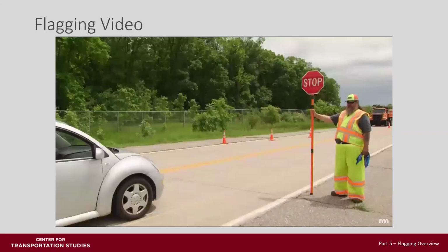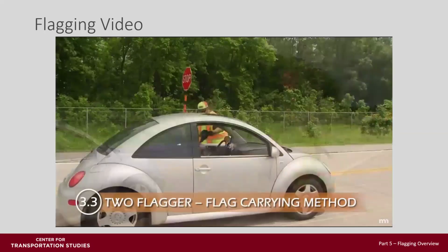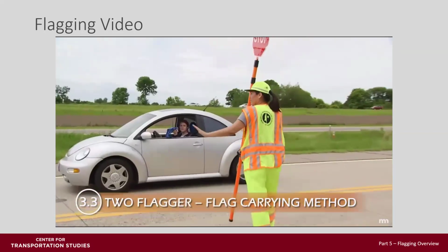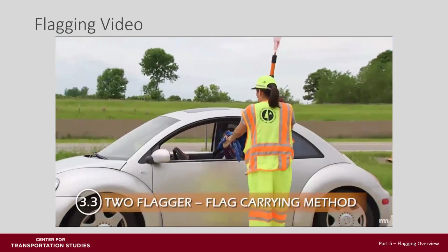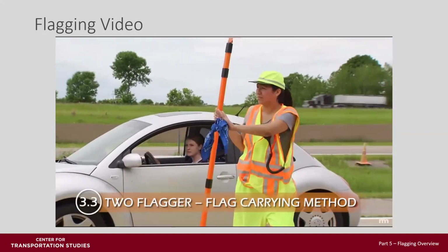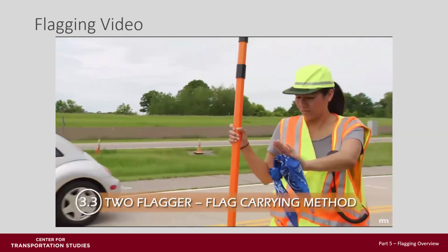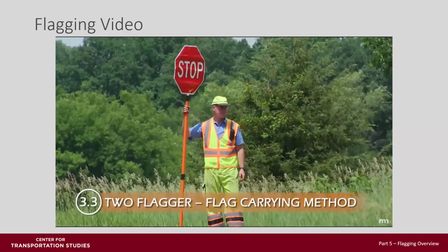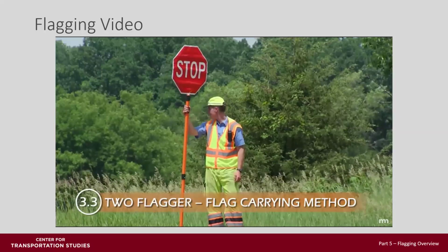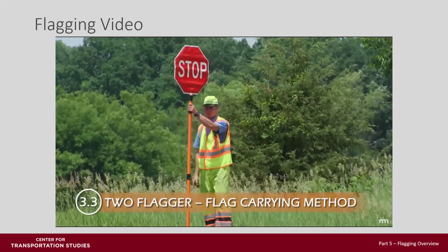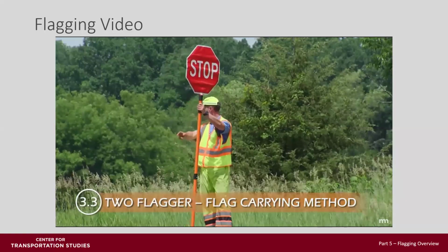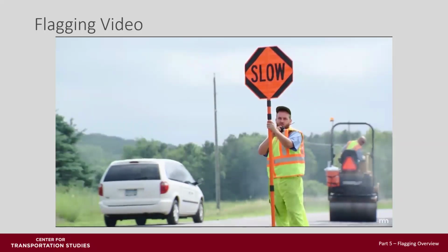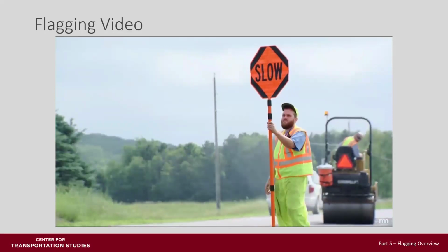between the flaggers. The first flagger hands a flag to the last car allowed to go through. When that car reaches the second flagger, he hands him the flag. Having received the all clear, the second flagger can now allow traffic to flow safely in the opposite direction. This operation is very simple, but the flagger must be assured that the driver of the last vehicle will pass the flag to the other flagger. Remember, communications between flaggers is vital, and radios are the best way to maintain communication.